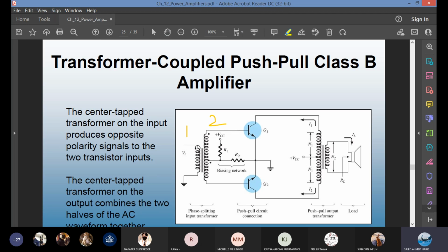You have an input signal, which is an AC. You know this connection from your diode application. This is called center tapping. When you center tap a transformer coil, it will split the incoming signal into 2 parts. One input becomes split into 2 half cycles.